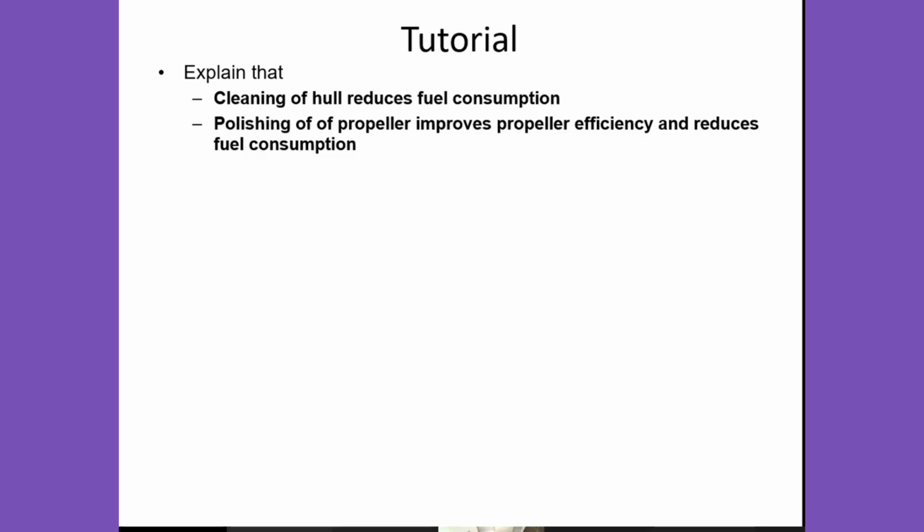It is the residuary resistance which increases with speed. That means residuary resistance can be a major part. In high speed crafts, it can be up to 60% of the total resistance, whereas the frictional resistance does not increase at the same rate.